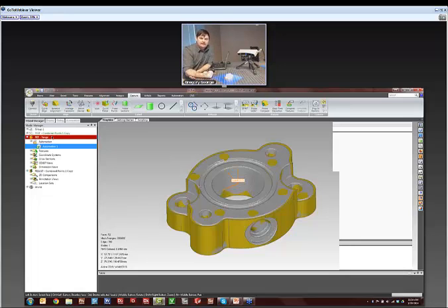Shiny and colors sometimes have issues, but I have had a lot of success so far with different surface finishes, especially with the option to run HDR mode, which essentially takes a bracketed shot. It'll take shots at different exposures and still be able to collect some data that's accurate.